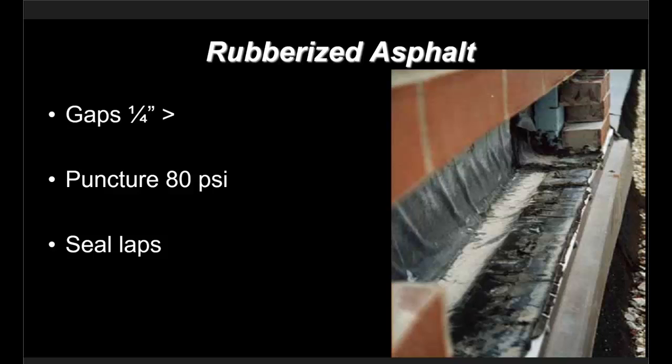How do you do it? Well, you can take this drip edge that's typically 3 inches and now bring it all the way back into your wall and up your horizontal. So when your flashing is coming down and sitting on top of this, it's going to be supported by this rigid piece of metal. The problem is, we were going to use peel and stick rubberized asphalt because we thought it was inexpensive. But now we're supporting it with this rigid piece of metal everywhere. It's no longer an inexpensive system.